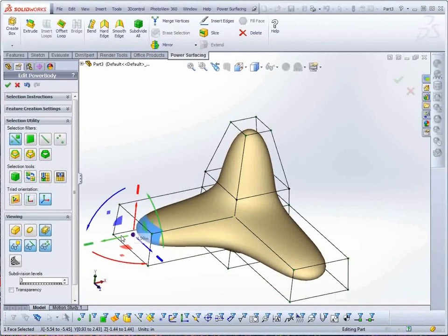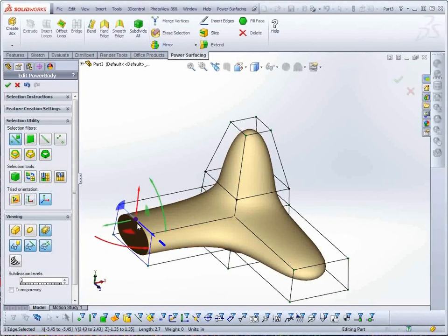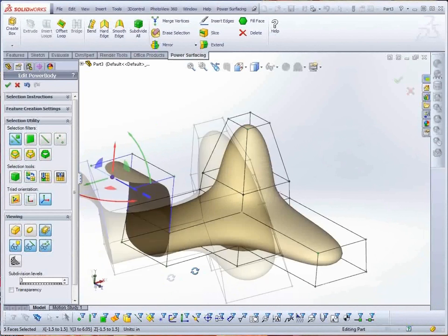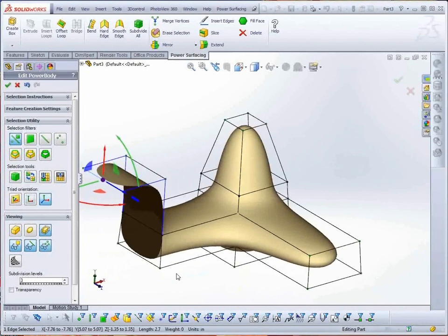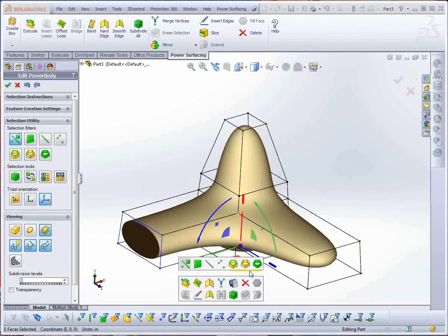The Quick Extrude also works on open edges, so if you are used to modeling with surfaces rather than volumes, you will probably find it quite useful. I'll delete a face to give me some open edges. Then select one of them and extend it by holding the A key down as I use the triad to move it. I'll do a few undos, and then cap it back up with the fill face from the right-click menu or from the toolbar.